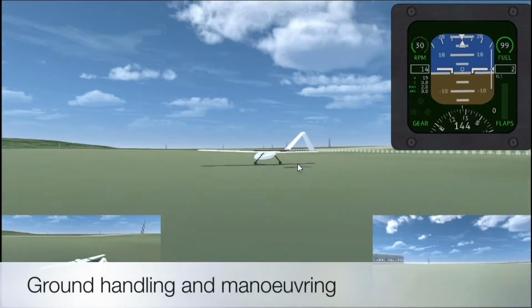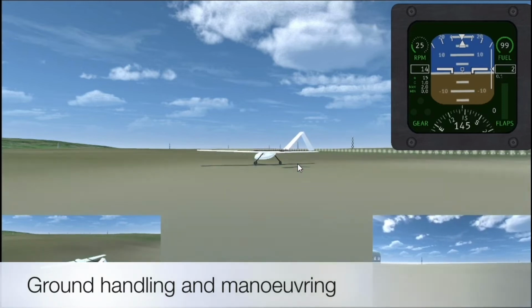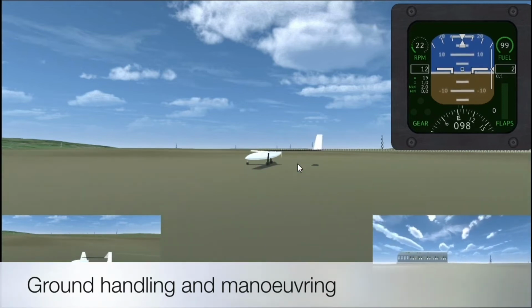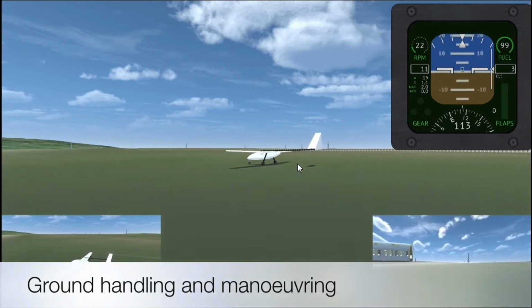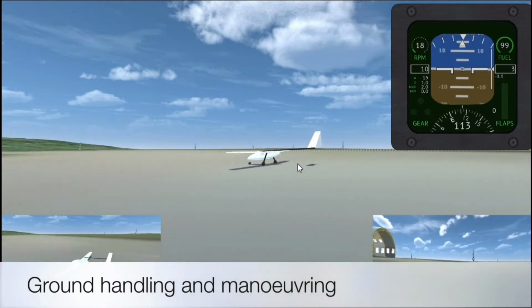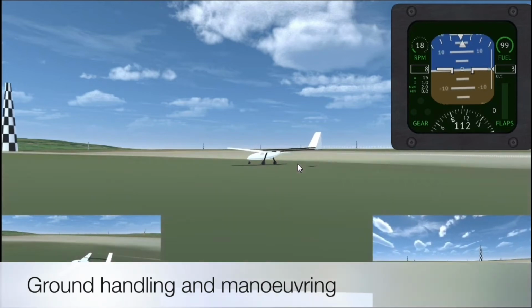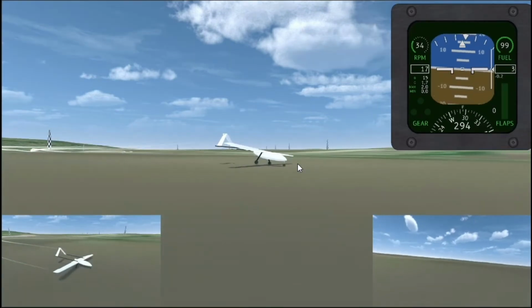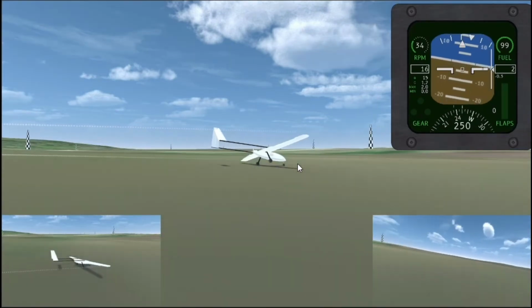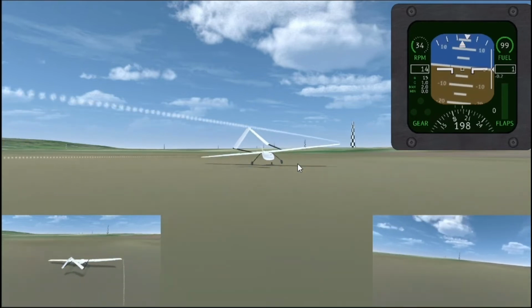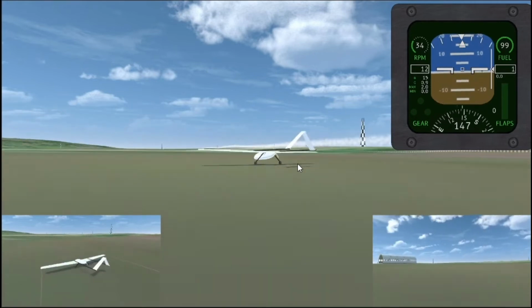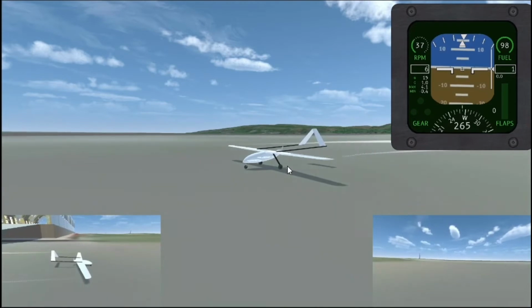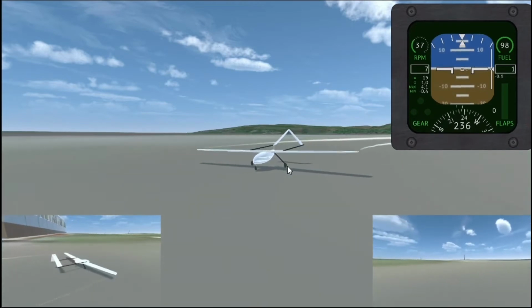The aircraft responds well to rudder inputs when manoeuvring the aircraft on the ground. As speed increases towards 10 meters per second, the rudder control results in a greater angular acceleration of the aircraft, which sometimes results in the wingtips dropping towards the ground, and the aircraft velocity vector is no longer aligned with the wheels, which results in the aircraft drifting. As a result, it is recommended that the aircraft maintains a slower speed at maximum of 5 meters per second